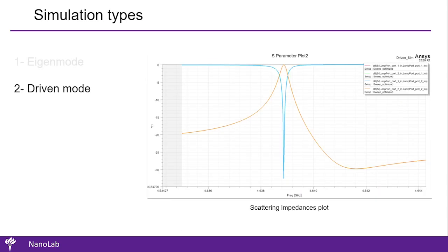Driven mode simulation, on the other hand, introduces excitations through external ports. This allows us to study how the structure responds to a real signal, letting us extract quantities like S parameters and visualize field propagation along the feed line.